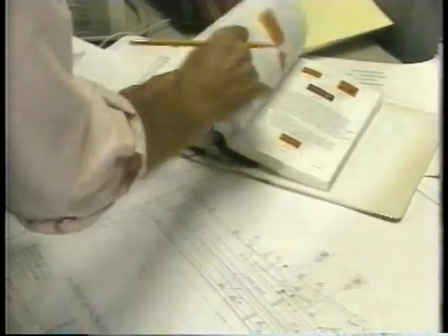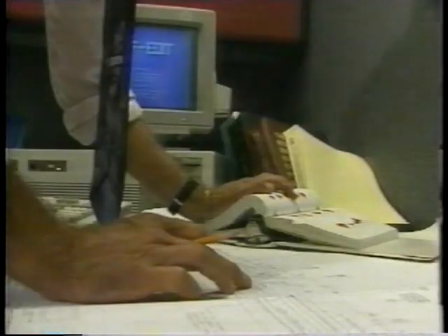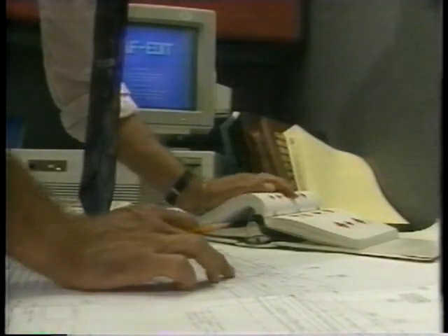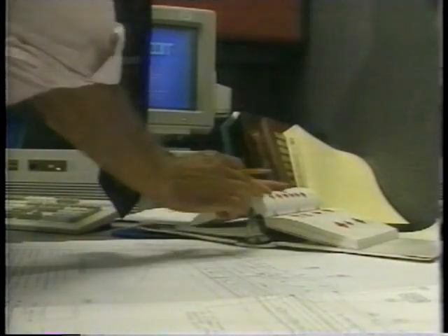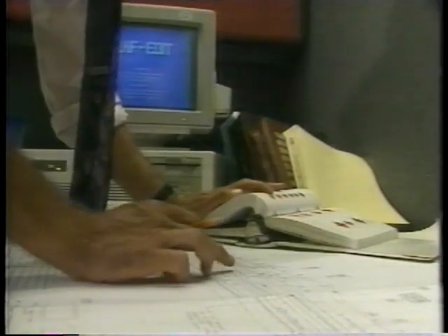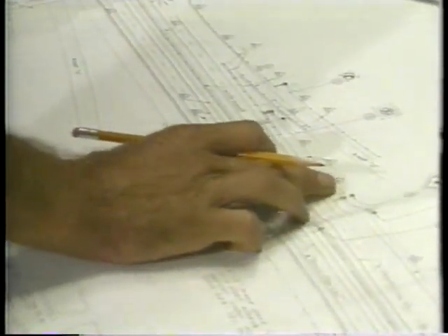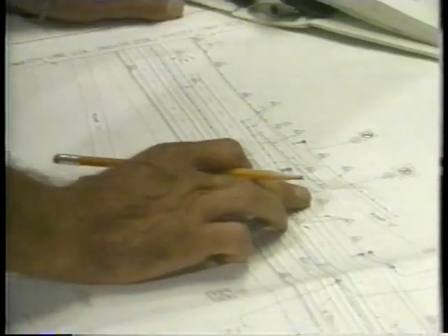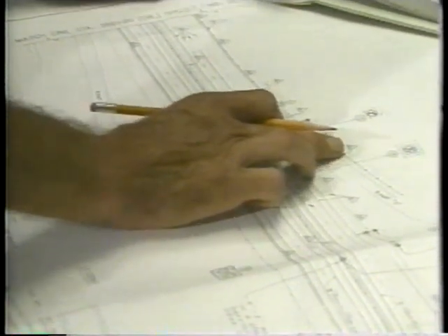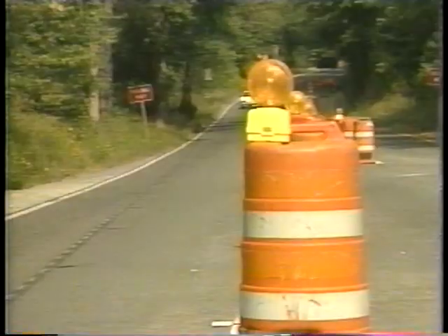It is often a legal requirement. In fact, it is required for all federal aid projects. It should include traffic control strategies, staffing requirements, use of specific devices, and design of geometric features such as tapers.